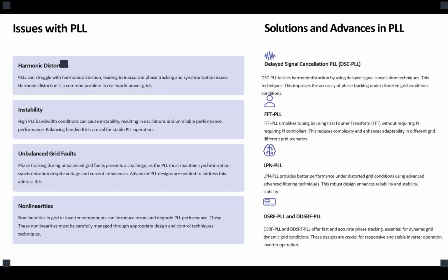Read about the Fourier series characteristics, and how different sinusoidal frequencies react when you multiply them with each other. Then you would find out that it's the only way you can turn a sinusoidal into a constant DC value, which was the purpose of the SRF: to multiply it by a sinusoidal with the same frequency.